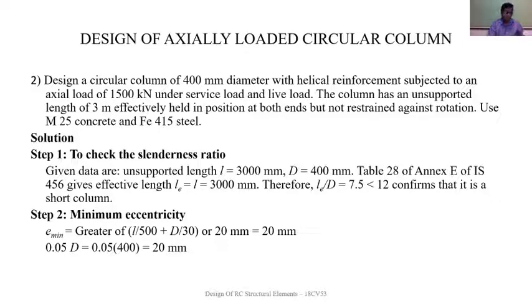So, in this design, determining the pitch of helical reinforcement plays a very important role. The volume of helical reinforcement and the volume of core need to be calculated in order to find out whether the specified ratio is within the codal norms or not.